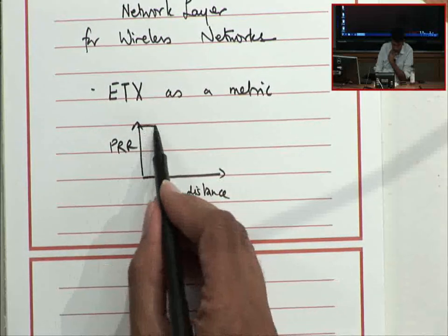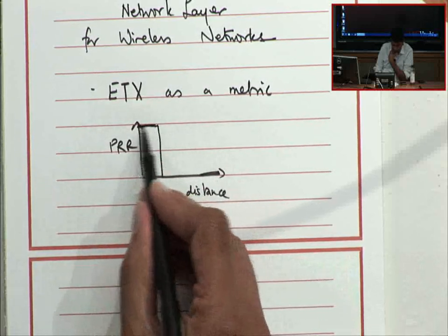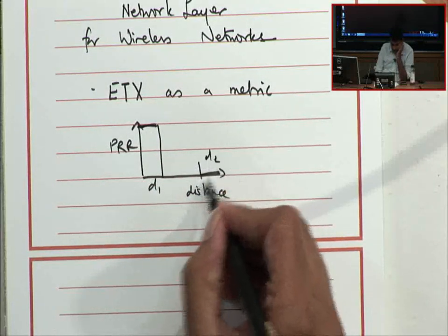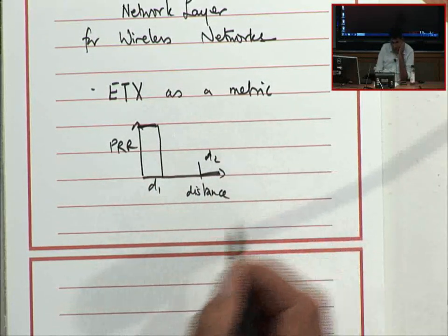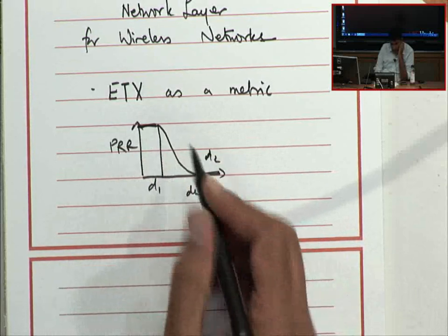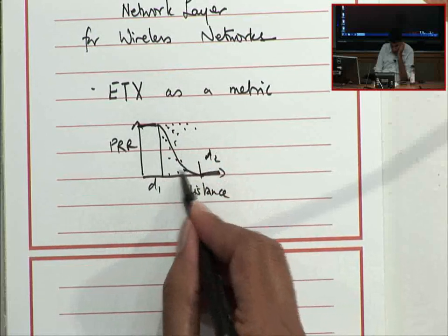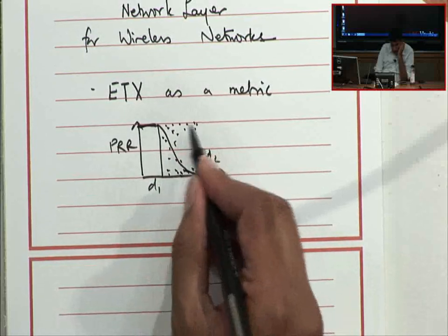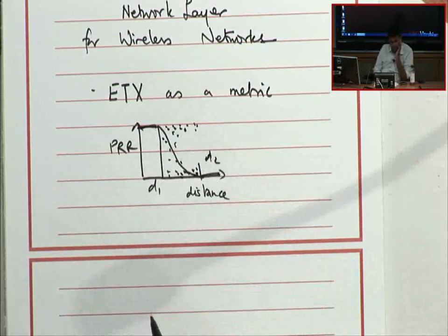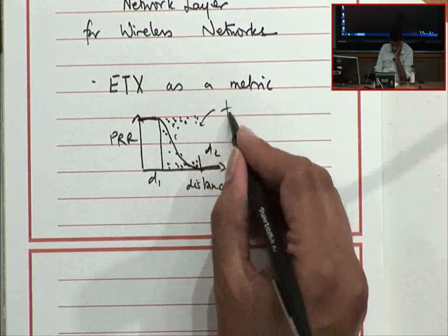And we identified that in real systems, there are these regions where, to the left of a certain distance, you get perfect link quality. To the right of a certain distance, you get almost no packets being received. In between, maybe the mean behavior kind of decays down, but really what you observe is a lot of statistical fluctuation of the link qualities, and often it's kind of bimodal between being high PRR and low PRR. So this is sometimes called the transitional region.